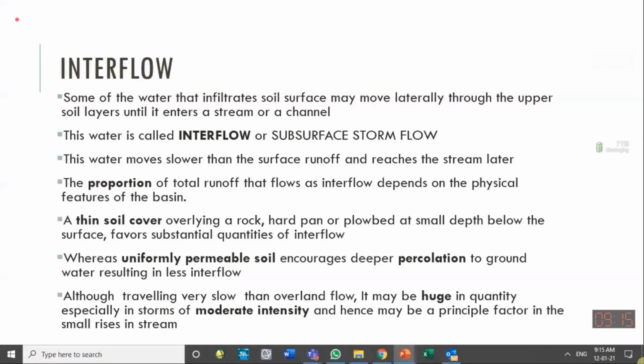The water is at atmospheric pressure. Above the water table line, the soil has some suction pressure, some negative pressure to attract water. If we put a pressure meter in the soil above the water table line, it will show some negative or vacuum pressure like a suction. It will be a small amount, but it tries to attract water because it is unsaturated.